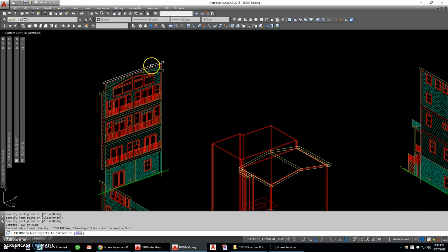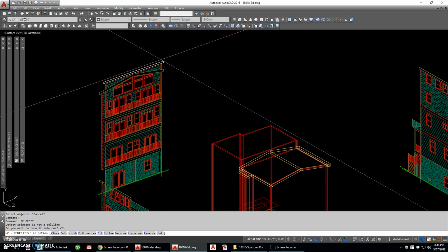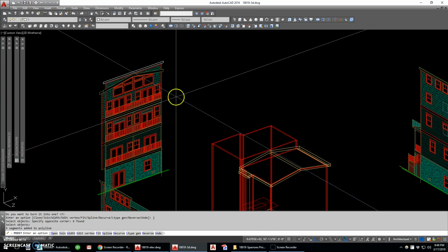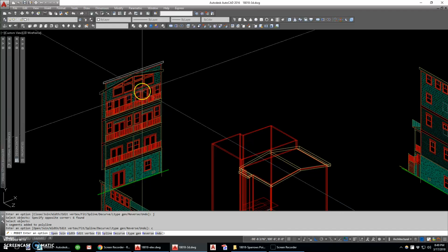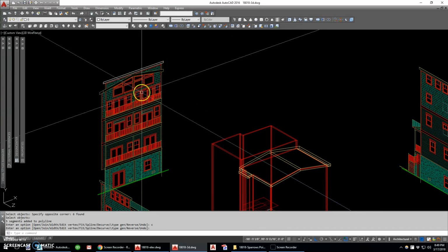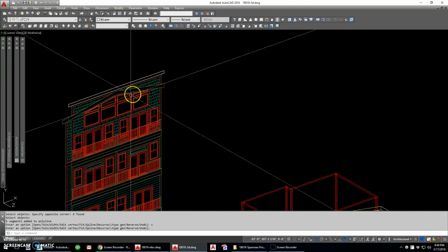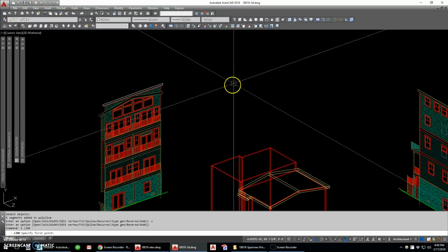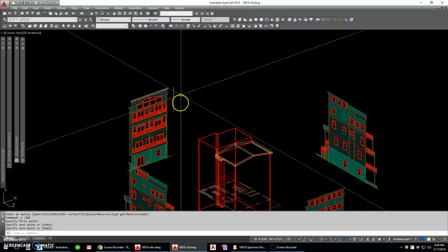Then what I'm going to do is extrude that. Whoops, I accidentally drew lines. Let me go ahead and do a PEDIT. Yes, join these things, and C for close. Polylines only work in a 2D plane. So the nice part is when I pick my back view and I start drawing a line, it looks like it's near the house, but I guarantee that that's near the 0 axis.